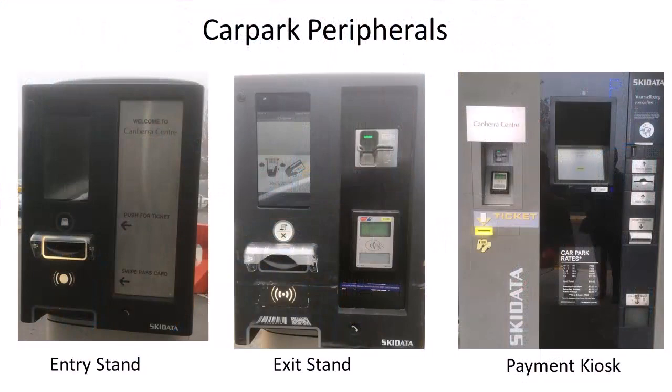For some systems, a really simple test bench is all that's required, while others may need a slightly more complex or elaborate test bench. Let's take a look at some of the types of things that a test bench needs to simulate. For many systems, the model test bench must simulate hardware components that may or may not yet exist. Things like sensors and actuators and mechanical systems can all be simulated by a model test bench, and this enables early testing of the software components that are being modeled independently of the hardware.